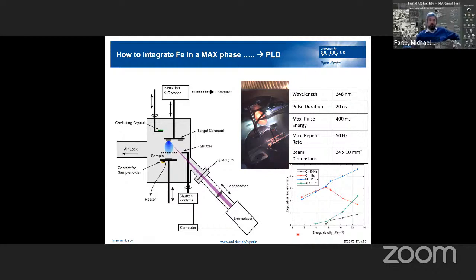Okay, so that's how pulsed laser deposition works. So you have a high intensity short pulse of an electromagnetic wave, which we call laser. This produces local heat here at the target, which is a composition target, usually an alloy target. You flip it from carbon to aluminum to chromium to iron, whatever you want. So it's a very rapid and quick deposition technique for producing homogeneous alloys. So this is quite well established. But for MAX phases, to my knowledge, Ulf Wiedwald used it for the first time.